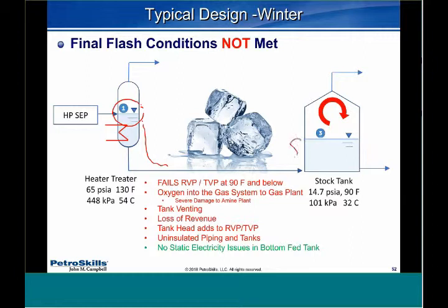You've got the head of the tank, and even if you're here at the top of the tank, with this particular fluid, 90 Fahrenheit, you'll bust. You won't make vapor pressure. And that's not wintertime. That's not very cold. In most places, we get a lot colder than that.